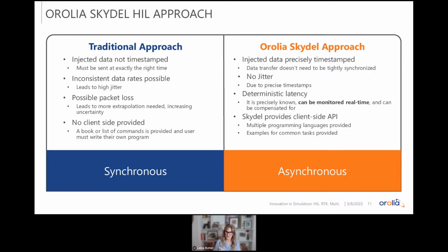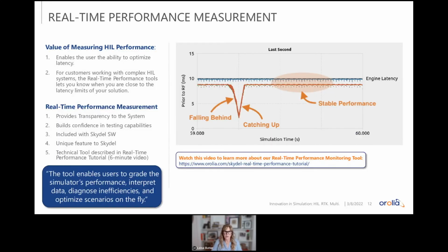In the Skydel system, we use an asynchronous approach, which means we're timestamping. We use the timestamp approach to control the jitter and make sure that we have deterministic latency, so we know what it is and we can actually compensate for it. So just know there are different methodologies out there. Be aware of that when you're working with a simulator, and that can help you determine the best way to optimize your system.